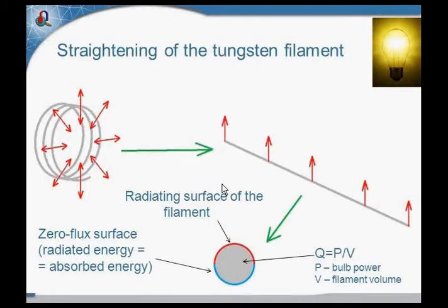And in terms of boundary conditions, we should divide our block. It's a plane parallel problem. And we should divide this block into two parts and set zero flux boundary conditions on the bottom part, and we should set radiating conditions on the rest part.